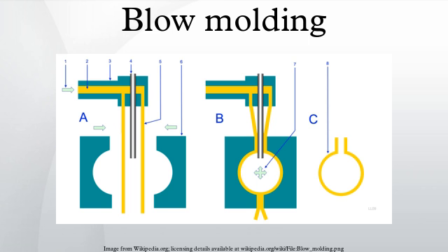Advantages: highly suitable for low volumes and short runs. As the preform is not released during the entire process, the preform wall thickness can be shaped to allow even wall thickness when blowing rectangular and non-round shapes. Disadvantages: restrictions on bottle design. Only a champagne base can be made for carbonated bottles.